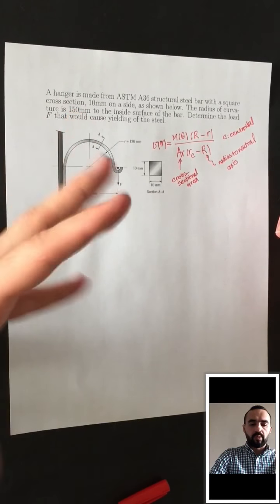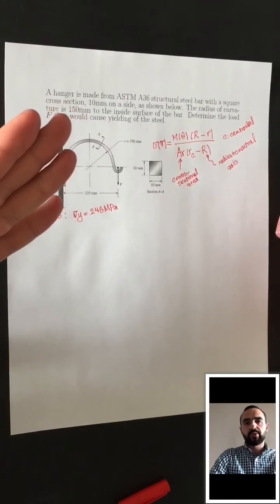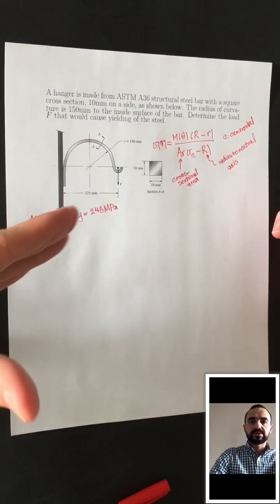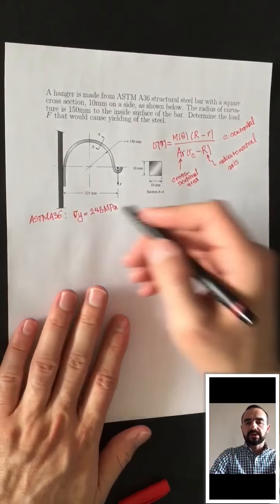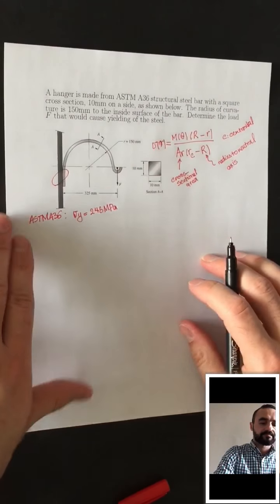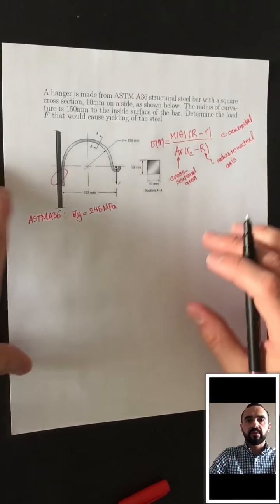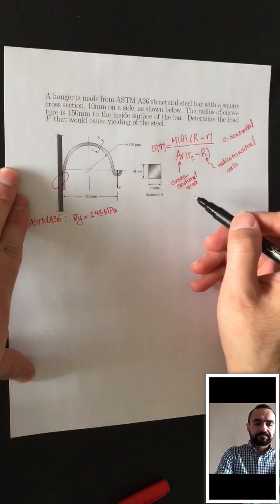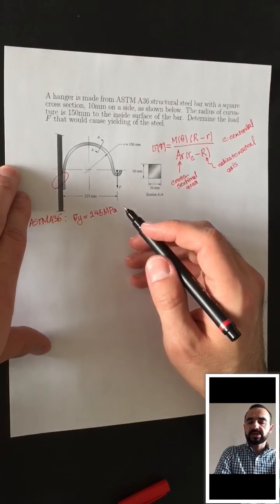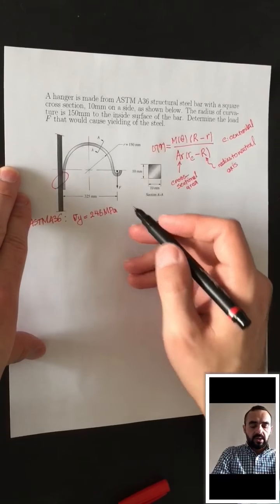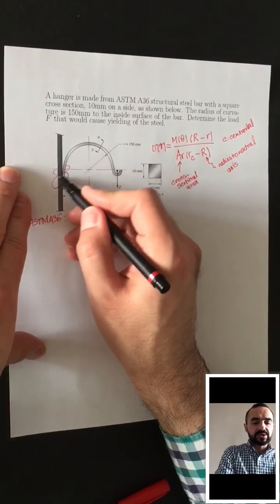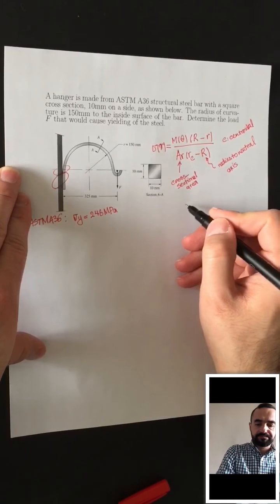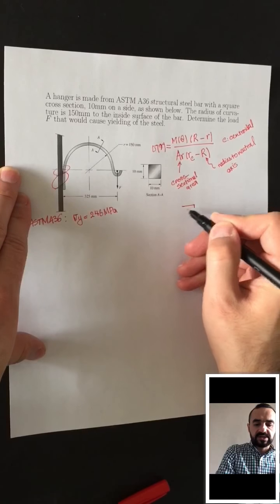Essentially, for any cantilever beam with an end load, the crucial section for normal stress due to bending is right at the support, meaning here. The difference between this beam and a straight beam is that for straight beams, the cross-sectional area is parallel to the wall. All right, so we need to transfer this force to this section and then compute its corresponding moment. Our desired section is this section,